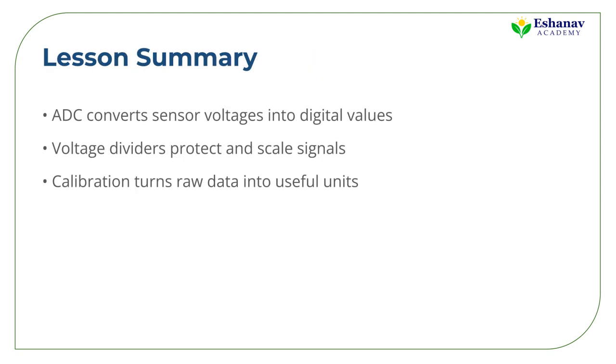In this lesson, you learned how the ESP32 ADC transforms analog voltages into usable digital data. You saw how to wire a simple voltage divider, read raw ADC values, convert them into volts, and then map them into meaningful units like light levels. Along the way, we covered pitfalls, calibration strategies, and practical design tips drawn from real-world automation projects. With this knowledge, you can now treat the ADC as a universal translator between the messy, analog real world and the clean, digital domain your ESP32 thrives in.